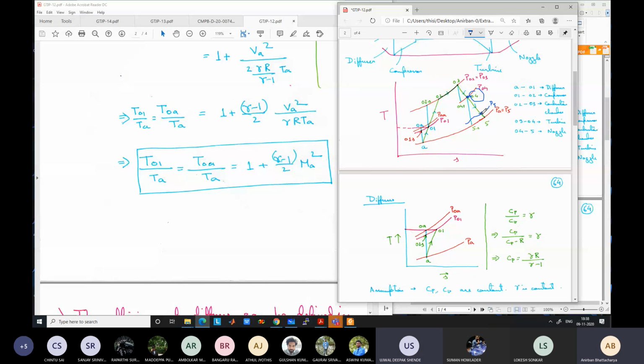Sir, if it is choked, then we have. It is choked. That's why this pressure is high. If it is not choked, we will be at this point, right? Only if it is choked can P5 be higher than PA, right? Otherwise, how can P5 be higher than PA? Is it possible that if it is not choked, P5 is higher than PA? It cannot be possible. So only if it is choked, P5 is higher than PA. It means there is a discrepancy between the atmospheric pressure and the exit pressure, or a jump is there.